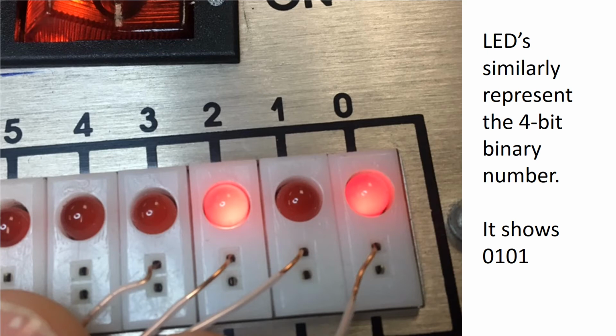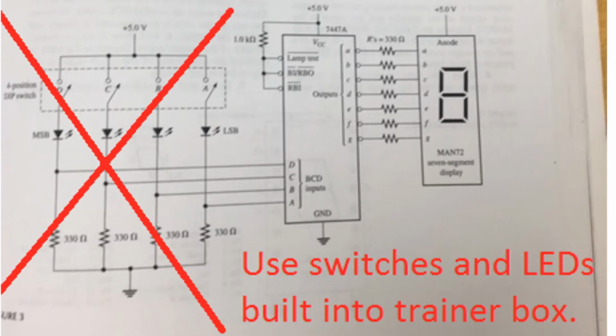And it shows 0101. Notice here that the digital trainer has the resistors built in. We don't have to add resistors between the switch and the LEDs for these LEDs. And here it is on the circuit diagram. You can see that the lab circuit diagram has 330 ohm resistors connecting to those indicator bits, the least significant bit to most significant bit.